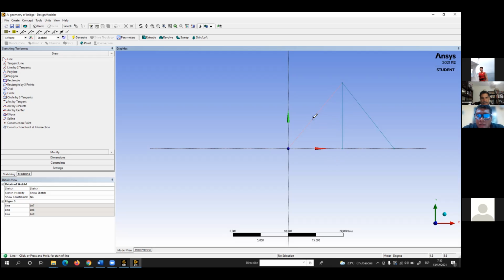Next, select this line, and from this line to the line of the axis. The letter V appears because this line is vertical. So click on that. Then you have to form the triangle, so draw other lines from this point to this point. Similar in the other part.